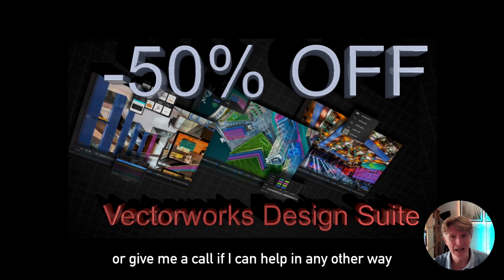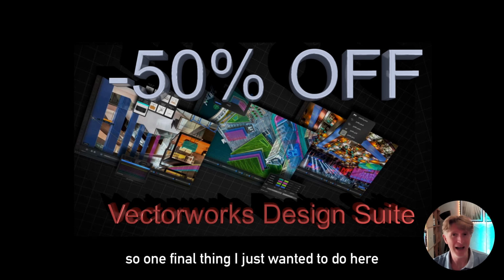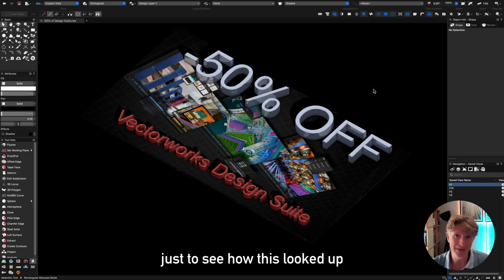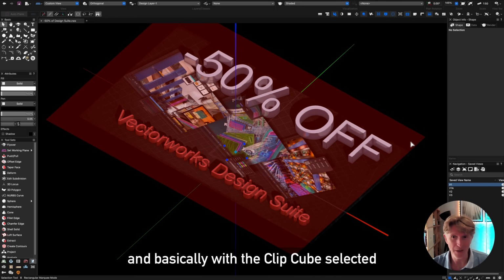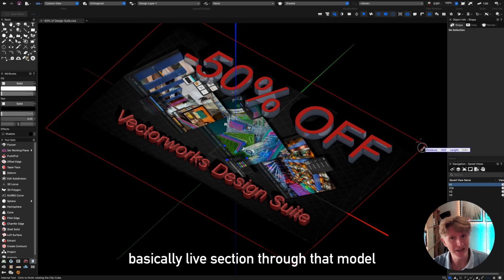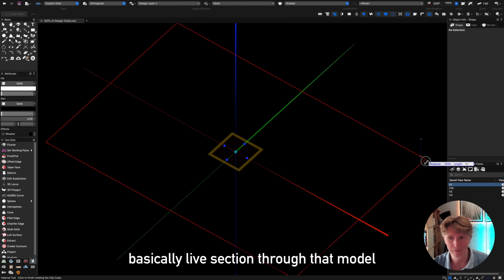So one final thing I just wanted to do here was touch on the clip cube just to see how this looked. Up on the mode bar, we've got the clip cube, and basically with the clip cube selected, you'll notice that you can actually live section through that model.